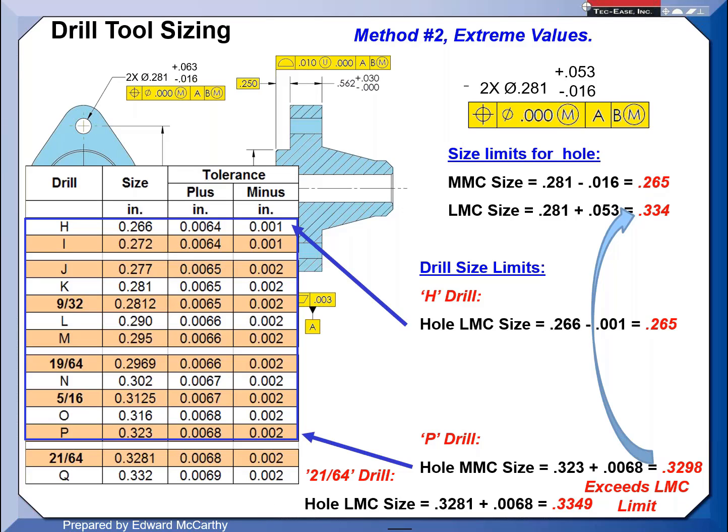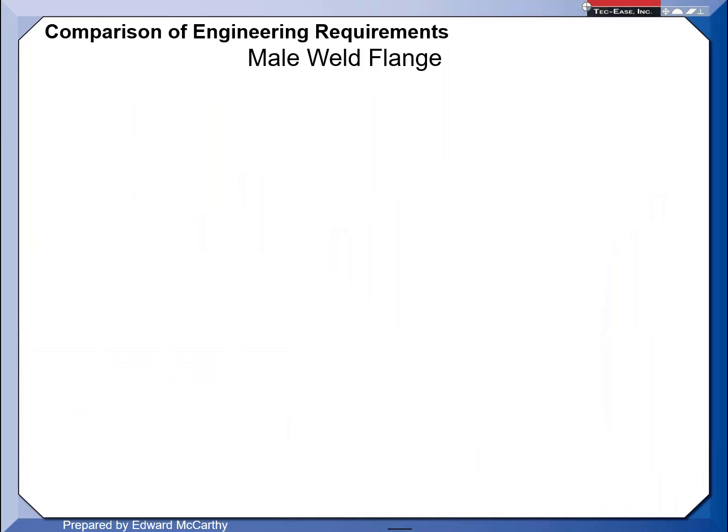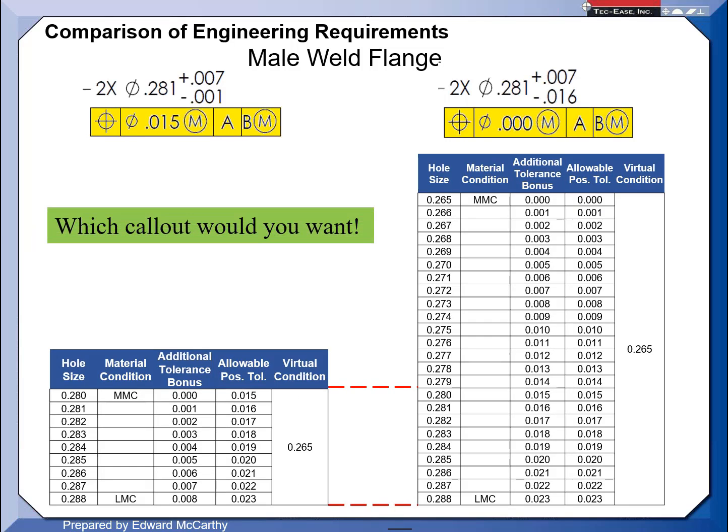They don't understand. And also, talking about the previous question, I would rather put both upper and lower limit in diameter. In this case, you see your maximum and least material condition right away. You don't have to calculate it. But it's my preference. Now, instead of 281 plus 7 minus 16, you can put 250, whatever, two different levels, and you will see least and maximum material condition right away.